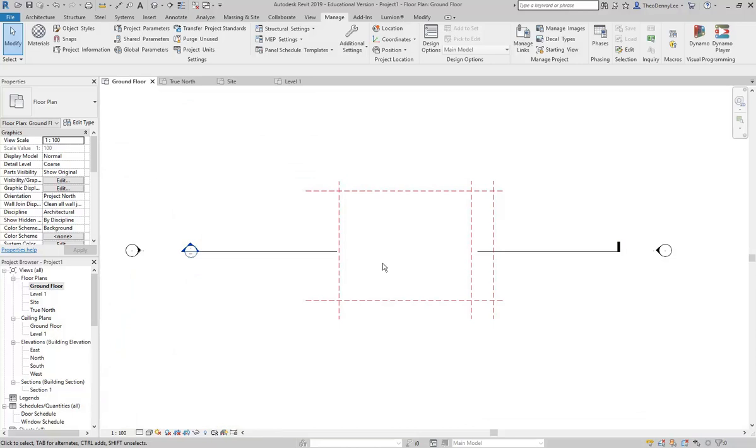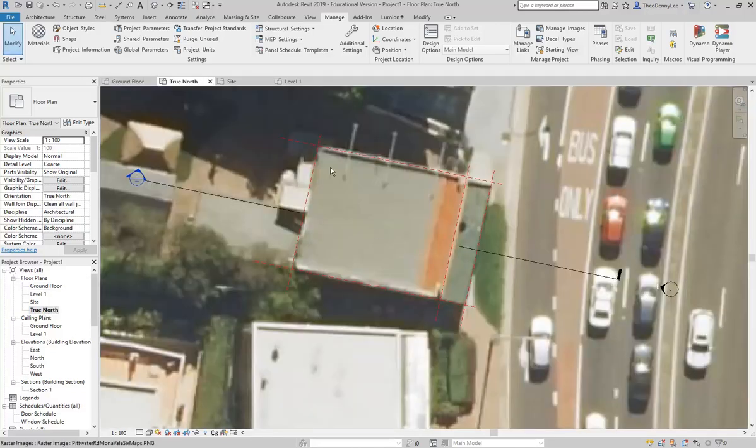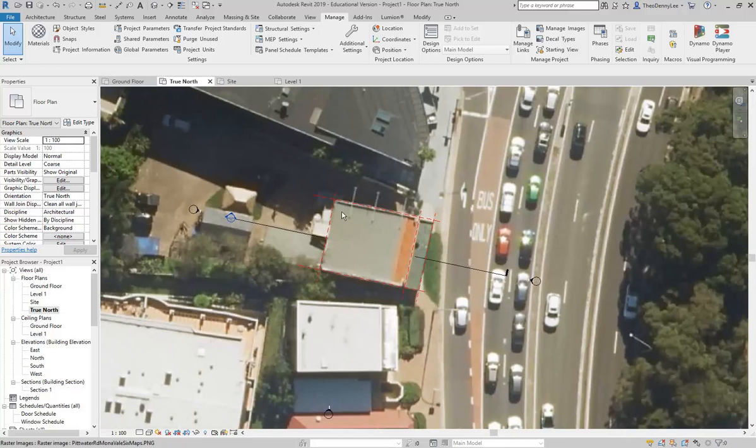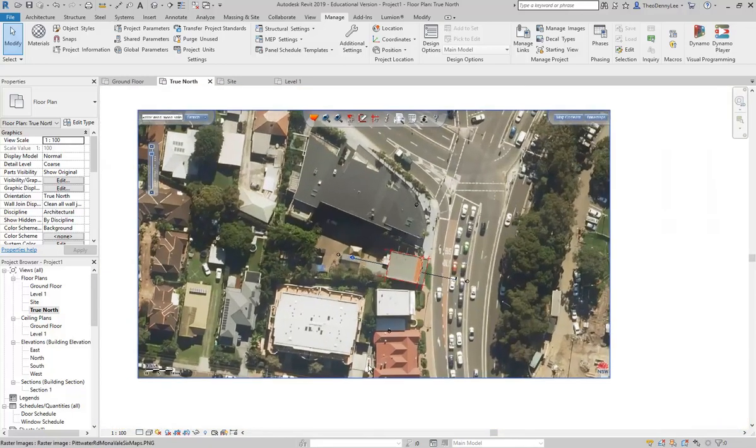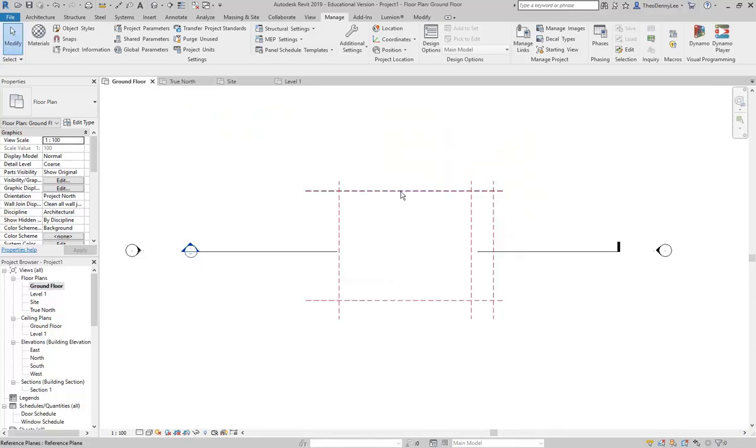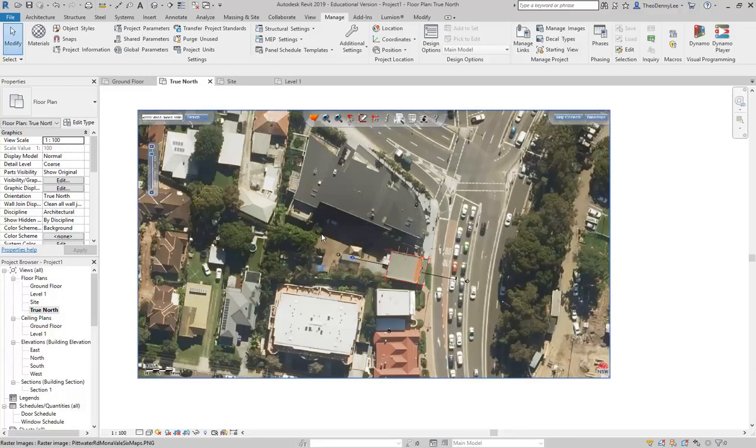That's correct. So have you seen how a survey looks? This is why I brought up site analysis plans earlier. They'll often begin with a survey or a more general site plan, and those are going to be like this. They'll be oriented to true north. But does that mean you should do your own site drawings that way? Should you always orient them to true north? No, definitely not. You're interior designers, or wanting to be. So you should do your drawings the way architects do them as well, which is to orient the building to your page, not to true north.